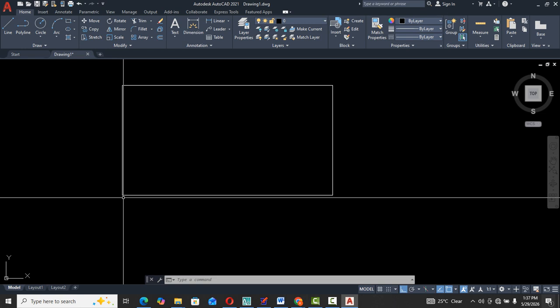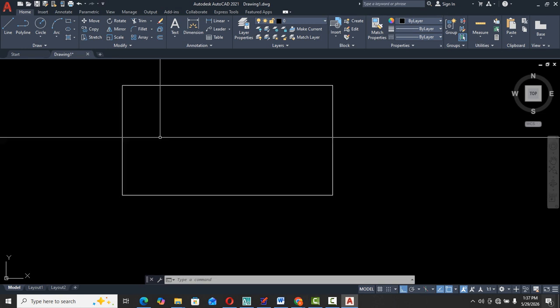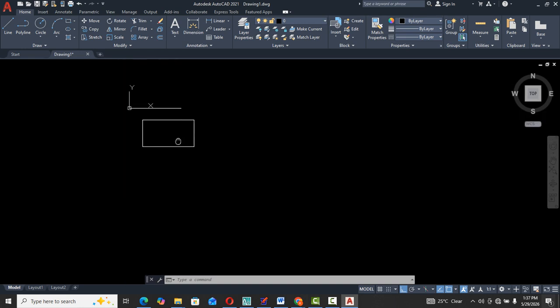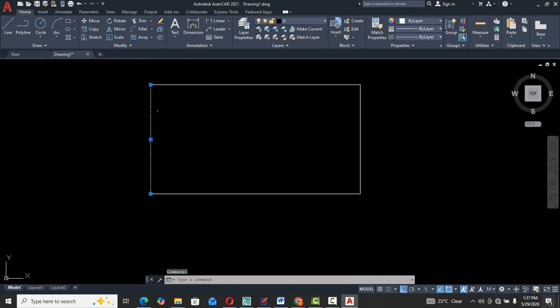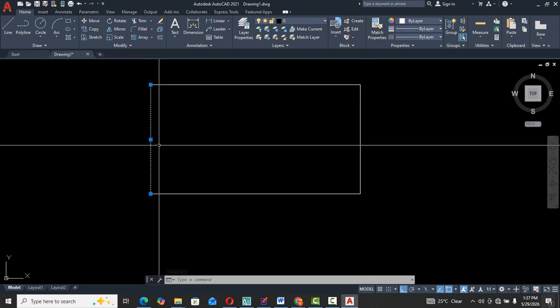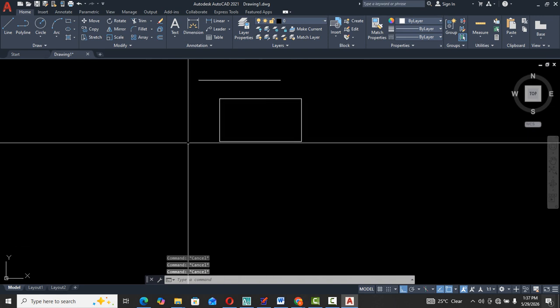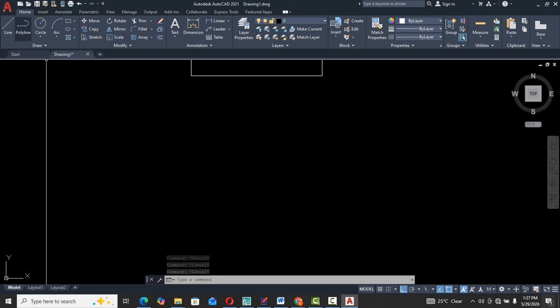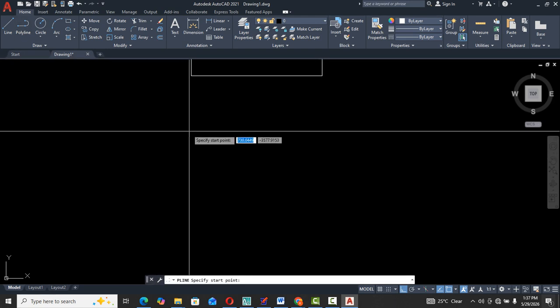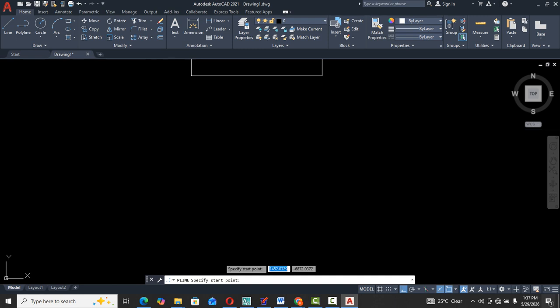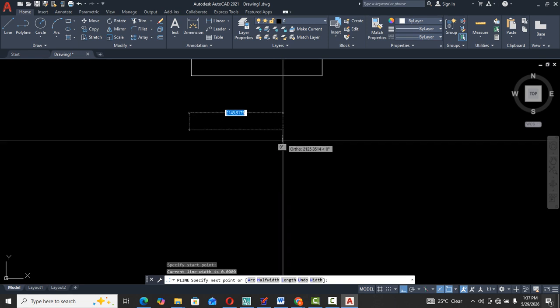So let's go back to polylines. Let's see what polylines is: the difference between polylines and lines. Let's go to lines first. You use line to create straight line segments. With line, you can create a series of continuous line segments. Each segment is a line object that can be edited separately. Is that clear? In other words, if you draw a line, you can edit each segment separately. For example, they have segment 1, 2 and segment 2, 3. If you select segment 1, 2, you can edit it without affecting segment 2, 3.